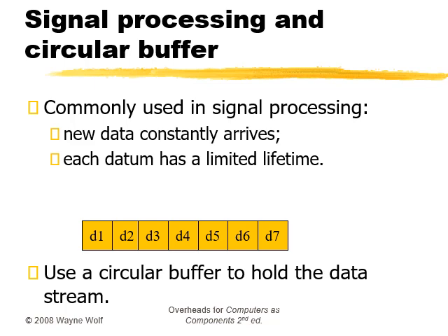So what we are going to do, we are going to use the head to move in time. The buffer points to the location at which the next sample will be placed. Every time we add a sample, we automatically override the oldest sample, which is the one that needs to be thrown out. When the pointer gets to the end of the buffer, it wraps around to the top. So let's check the example of this.